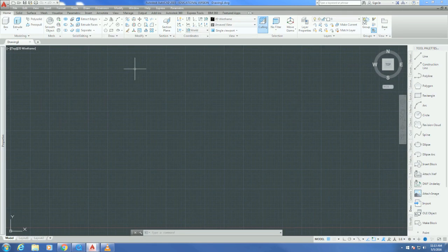Some important things to note is right here is your toolbar, and then down here is another toolbar which comes in handy very often. So right here we're looking at display grid. If we turn this off, we have no grid behind us. I like to work with the grid, so I'm going to keep it on for this video. Right next to that is the snap mode. That's another helpful tool. Right now we can draw lines anywhere we want. If we turn this on, it'll snap to a corner, which is really helpful when you're drawing things.